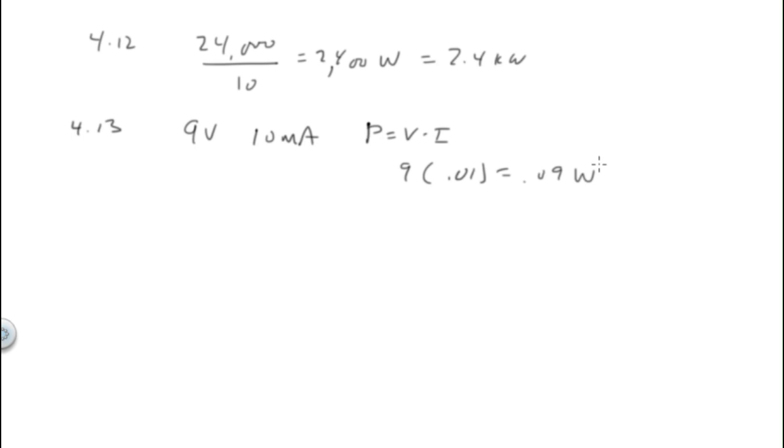14. Okay, so we have now, find the power dissipated in the 5K resistor and the 15K resistor of figure 420A. This is 14. So basically, if we know I, I is equal to 20 volts over 20K, or 1 milliamp. So I now know my I.